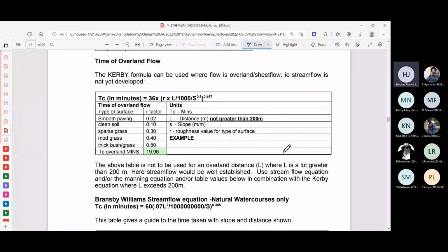That's the Kirby formula, and you can see the runoff coefficients again for that. Okay, we've got the slope. So I was in error there. It's related to the runoff coefficient. Okay, it's not the slope of the catchment. When we're working off the runoff coefficient for the catchment area, then we'll need that slope over there, 4.1%.